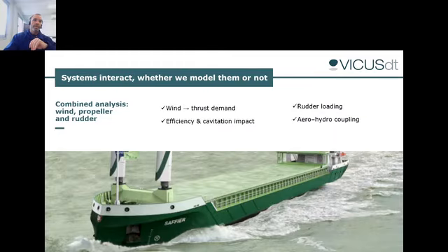So when you are comparing, there is also the impact that it might have on your propeller performance from the point of view of cavitation. That is, you are changing the advance rate of the propeller because of the reduced resistance of the vessel, or because of this rudder impact, no?